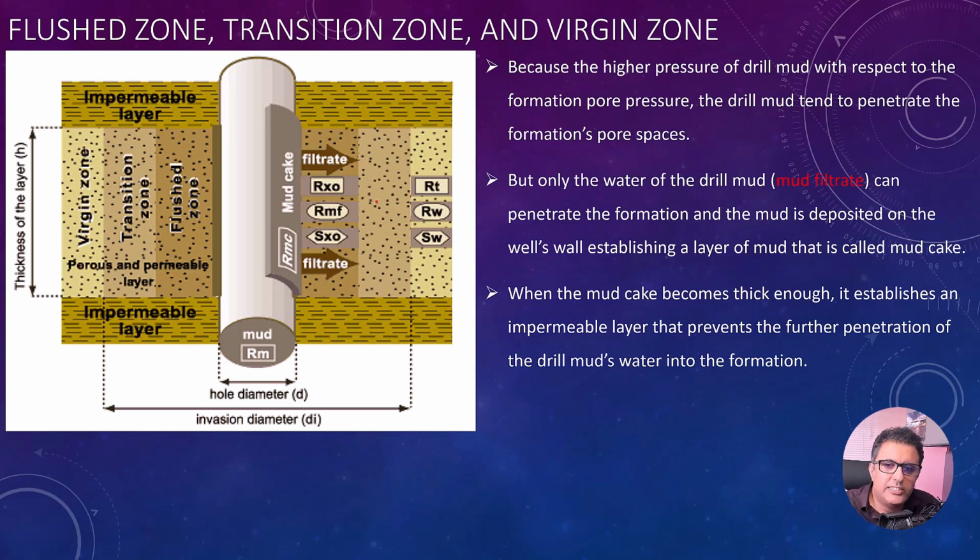Previously, I mentioned that during drilling, we have the mud pressure, PM, and then in the reservoir, we have fluid pressure, PF, and usually PF is always smaller than PM. As a result, the mud tends to penetrate the formation.